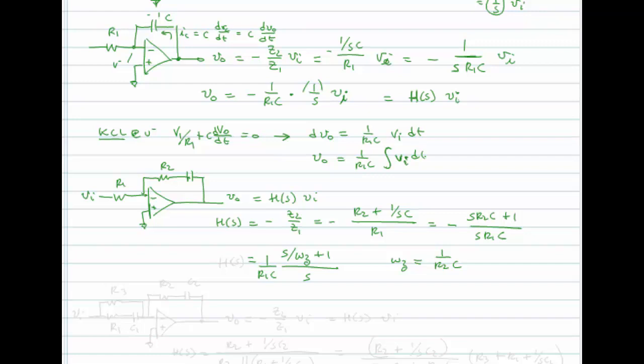So this goes back to when we were doing the sinusoidal steady-state response, and we were saying, okay, let's excite some system with an input VI that's sinusoidal, cosine omega t. What is the steady-state response Vout? And we found that all we had to do was to find the magnitude and the angle of H of S, the transfer function, evaluated at the frequency that we were exciting the system at. And here you can do the same thing.